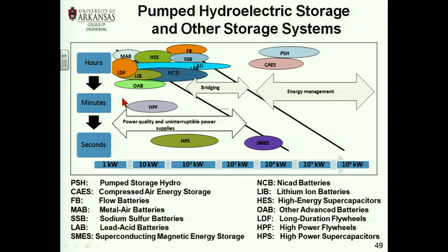Sodium sulfur batteries, SSB, here. Well, the sodium sulfur battery, they've been taken out. The sodium is heated up to 300 degrees centigrade, and they have had some fires, so they have been taken out of the market for a while, right? Float batteries, these are good, they should be here, right? They give you a lot of energy and power. The problem with the float batteries, basically efficiencies are about 80%.